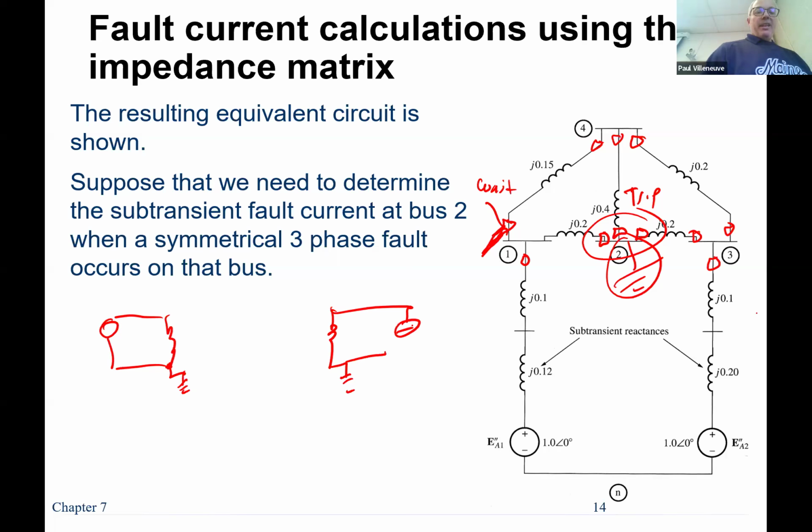What ended up happening is you had current going through here and then bypassing through ground and going back over here, and it wasn't going back through the other differential coil. So one said, hey, let's go ahead and operate. And then the other coil, which was the restraint coil, didn't restrain it. So it said, yep, we've got to go ahead and trip. Ground screws, literally a little copper screw, can kill you.